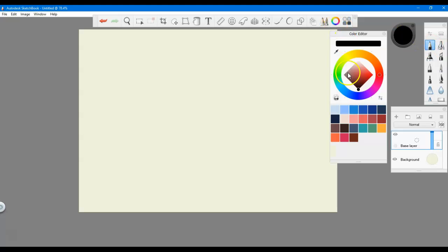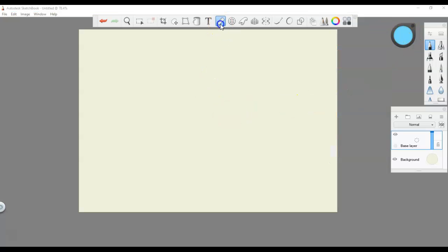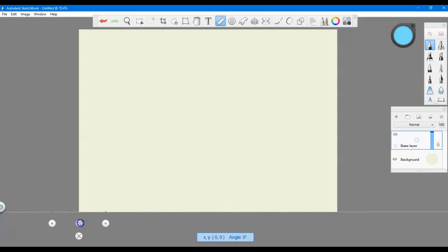We pick our pen, and then we're going to pick a light blue colour. It's a traditional drawing colour. The reason why we used to draw in light blue is when we did an overlay over the top and we did it in black, or when we were printing, you could draw in black, and then when you printed it, it wouldn't pick up the blue colour.